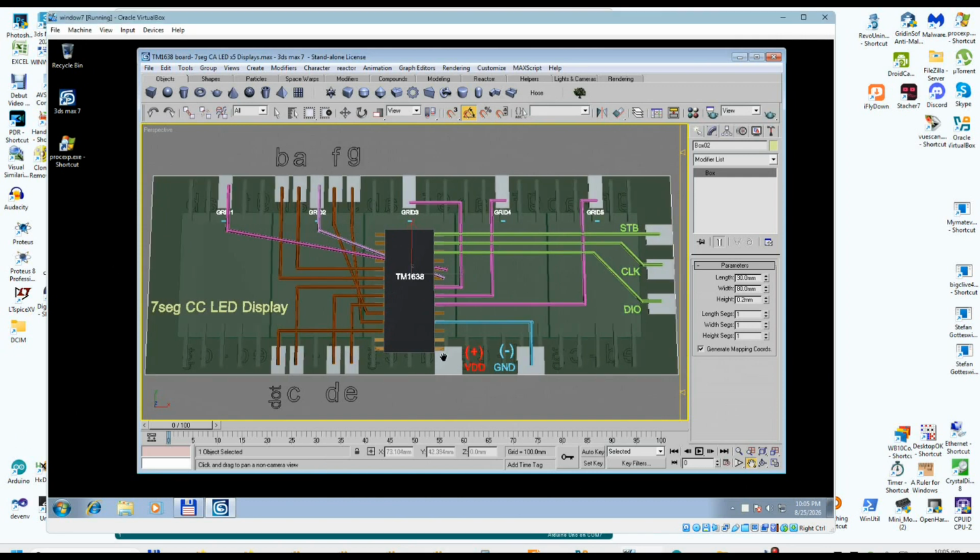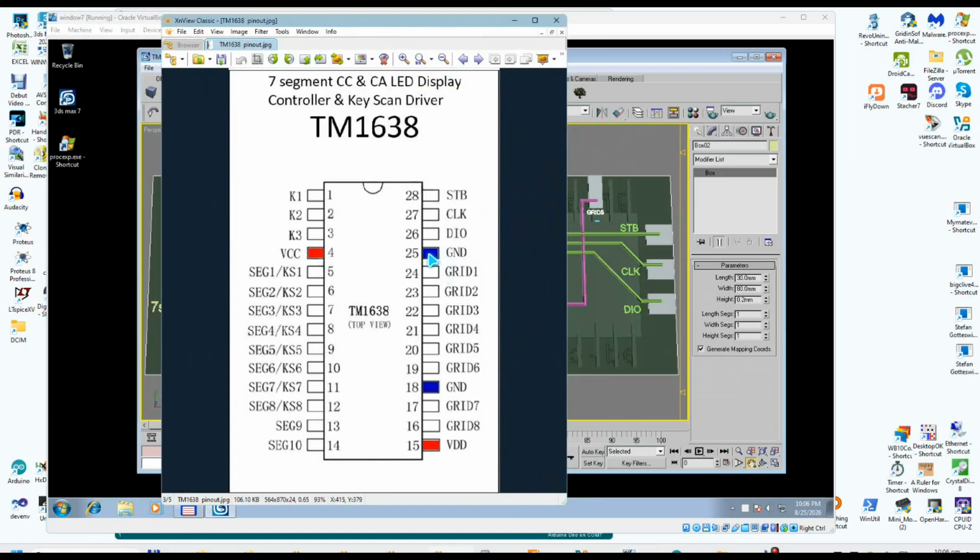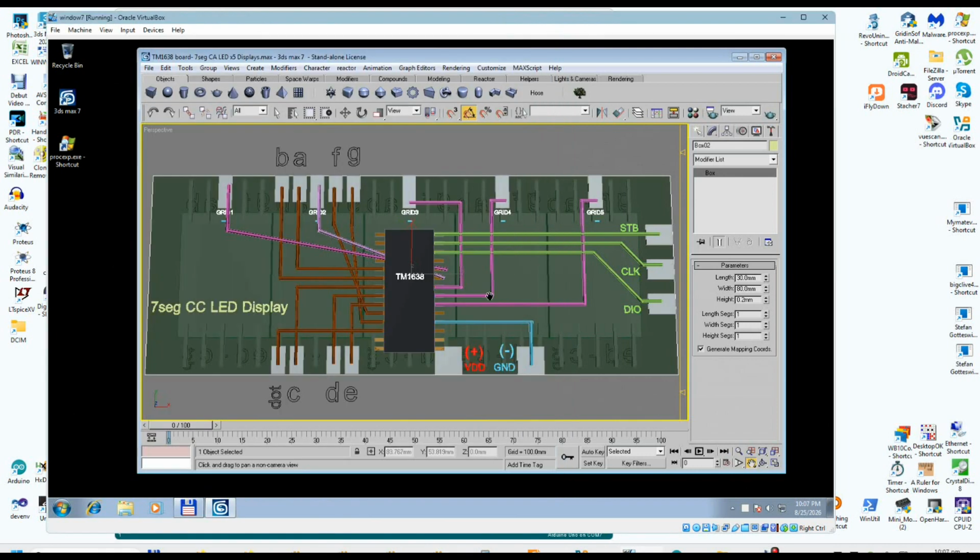And this is the positive pin of the chip, the negative pin of the chip. As you can see here, they are the same. I actually measured them with the multimeter set on continuity. The ground pins are common internally, it's a single rail. The same goes for VCC, the positive rail is also common, the same rail inside. So it doesn't matter where you power it, it's doing the same thing. You don't have to power it from 2 different power sources or 2 5-volt supplies. Only one is enough, because it's literally one wire inside for the positive rail and one single wire for the negative rail inside the chip. That's it for the 3D view.